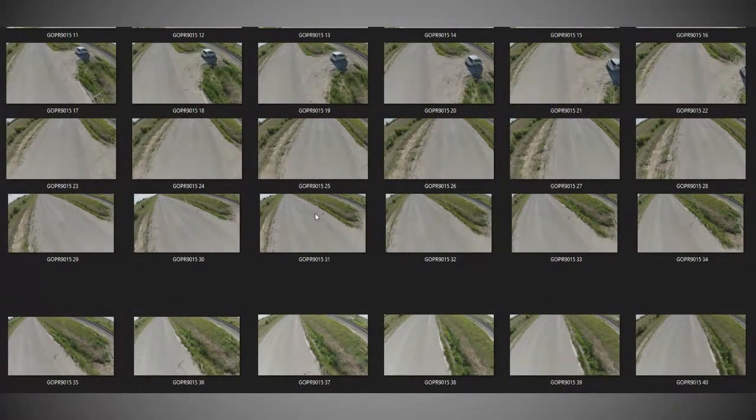And one thing you could have done that I was talking about in the previous section is, as you're walking down the road, you can also turn around and come back the other way. So you get some really good overlap, and then you get basically perspectives from both sides of the roadway. Now, that's only useful really if, for example, the car was off to the side, and I moved one way, so you'll see one side of it will work well when it gets reconstructed, but the back side where I didn't have anything is just going to be a mess. It's just going to try and fill in the holes or whatever, and it's not going to look that great.